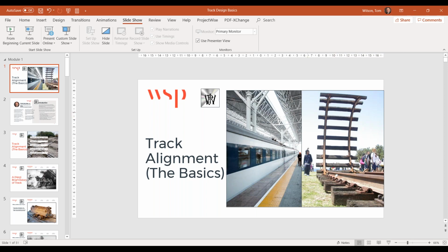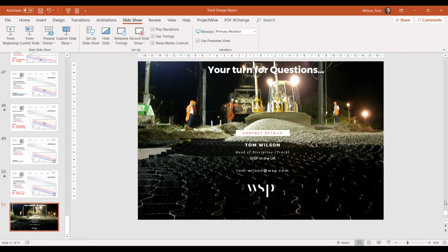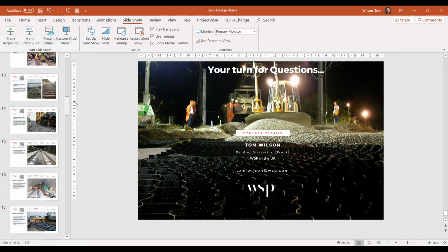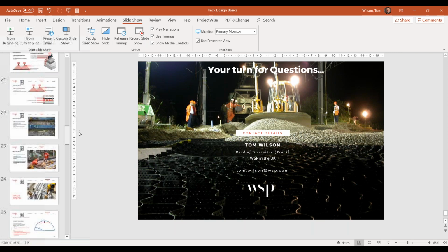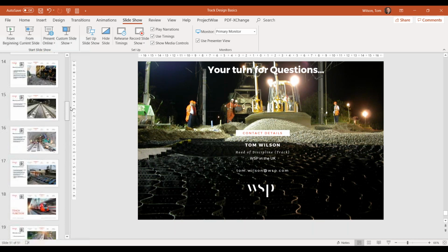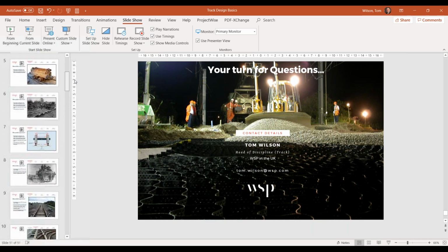Right, we've got a couple more questions. Okay. Next one's from me, actually, Tom. As I was looking at the VTrans photograph, and you showed it going into a longitudinal underbridge deck type of thing, I noticed there were gabion style baskets, longitudinal baskets in the cess area, creating what looked like a kind of ground beam, and it looked a pretty good idea. So have you ever been involved in either specifying, designing or actually installing that type of solution?